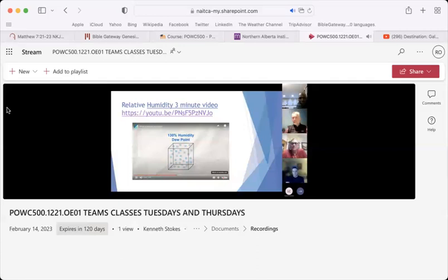Everything above 100 isn't able to stay inside the air and will condense into water droplets, giving us things like morning dew, fog, rain, or annoying cold blasts. But how can we reach such high levels of humidity? Remember, relative humidity is linked to the air temperature. If we take, for example, air at 30 C with relative humidity of 33% and cool it down to 10 C, the humidity will rise to 100%.